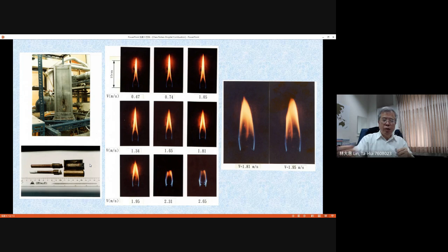We supply the liquid fuel from the upper semi solid cylinder through the sponge, and the liquid fuel flows out and basically forms a very thin liquid film flowing along the surface of the cylinder. Then it flows downstream to the lower, empty, hollow semi cylinder.